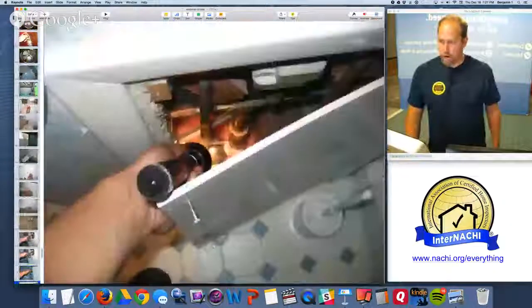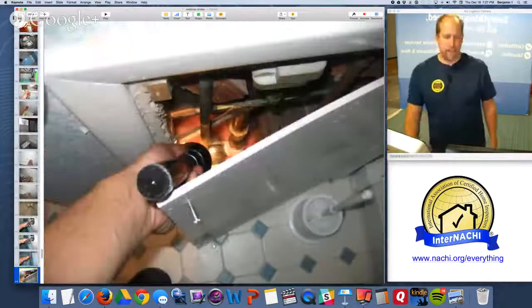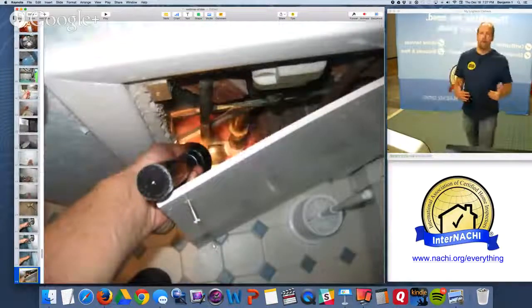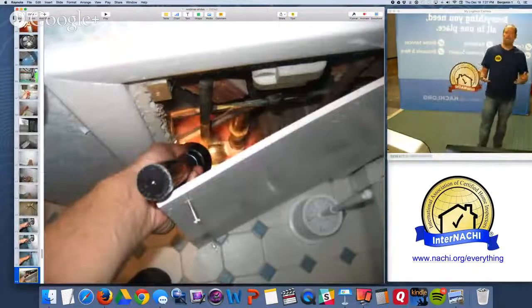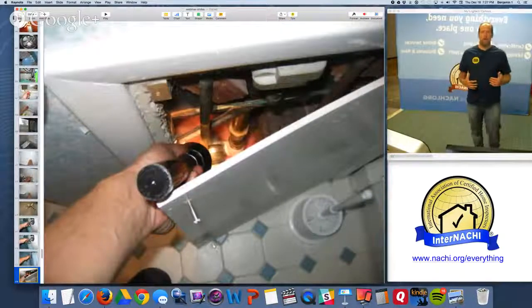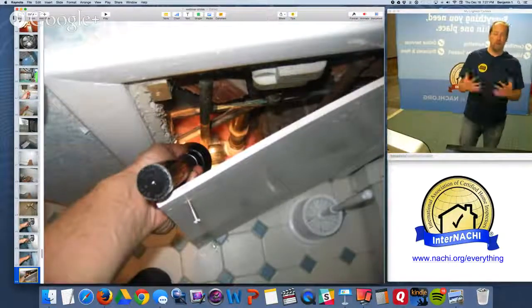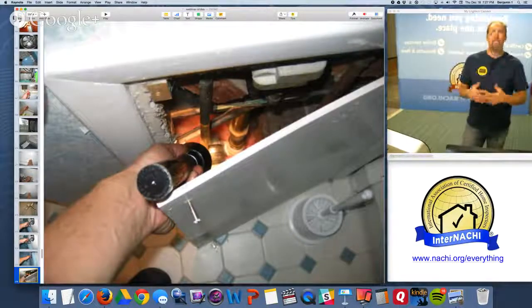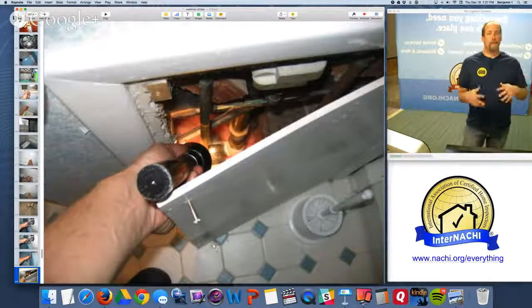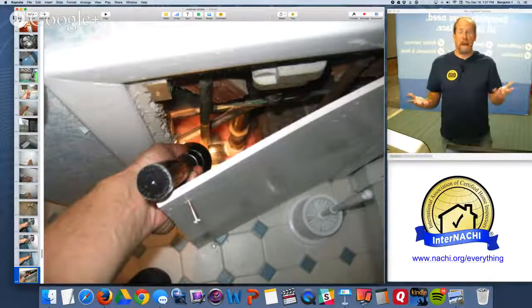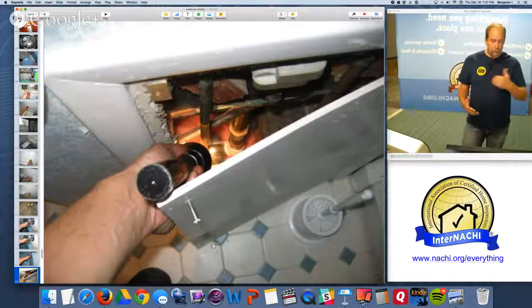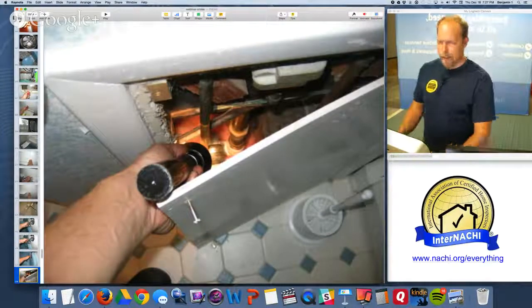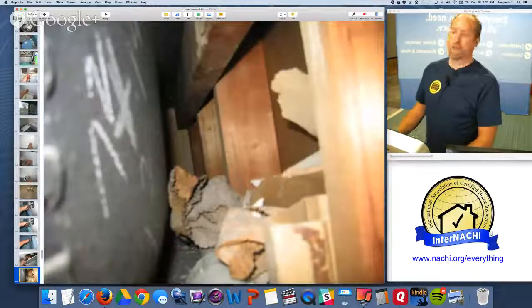So all that works. I love to open the plumbing access panel. I think every tub and shower should have a plumbing access panel for inspection. It should be a routine maintenance kind of thing for every homeowner to do, because you don't necessarily see the water leaks, but they're happening above the plaster or above the drywall. So I pull open that and I take a look at the trap and the fixtures and the pipes, and everything looks good on this house.